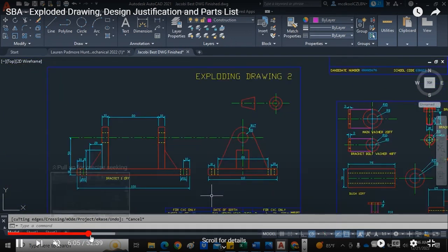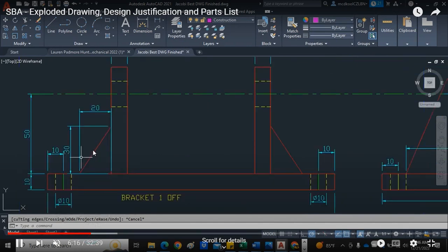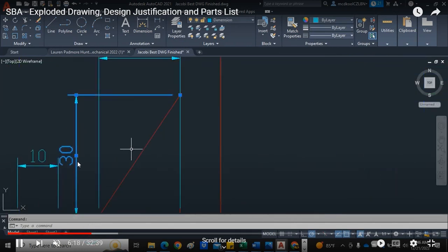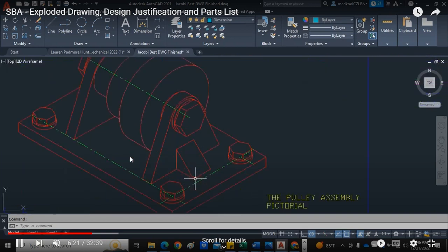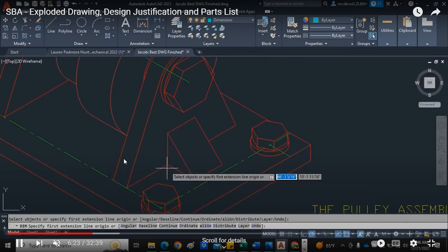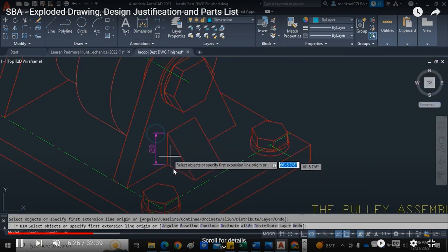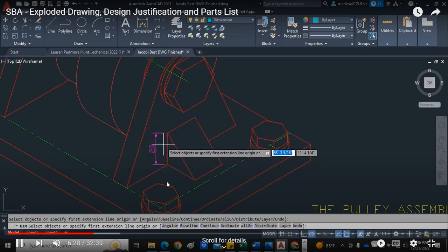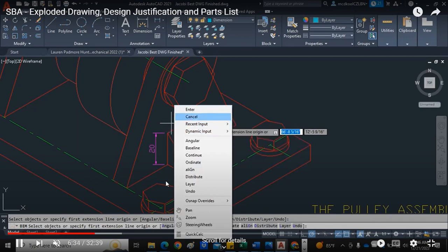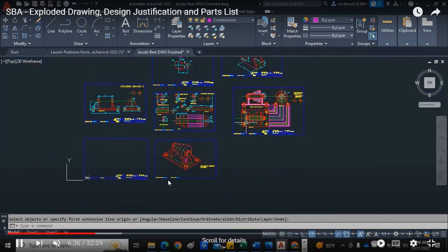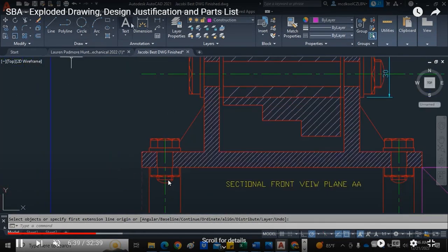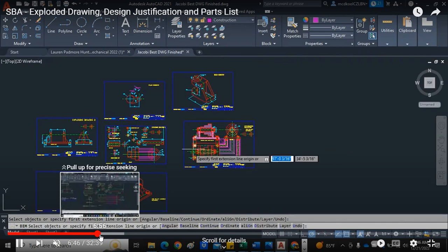So what I did here was I looked at the height of this. So this person has that the web is 30. The height of it is 30, but when I come over here, the height of this is 20, so you will lose a mark there. So all I'm saying is that you need to make sure that the measurements that are in your drawing, in your views, they must line up. However, in this view, the person has the measurement here at 30. So just make sure that they line up.